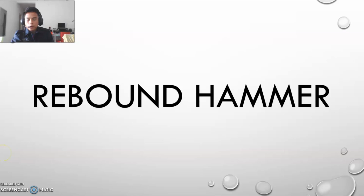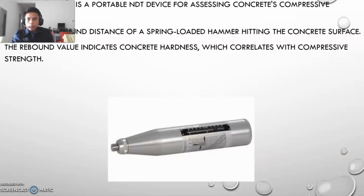First testing is rebound hammer. Rebound hammer is a portable NDT device for assessing concrete compressive strength. It measures the rebound distance of a spring-loaded hammer hitting the concrete surface. The rebound value indicates concrete hardness, which correlates with compressive strength.